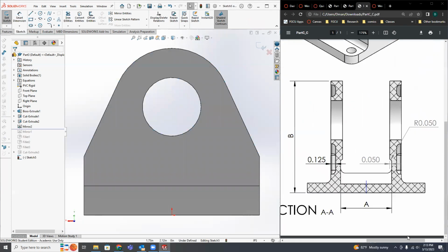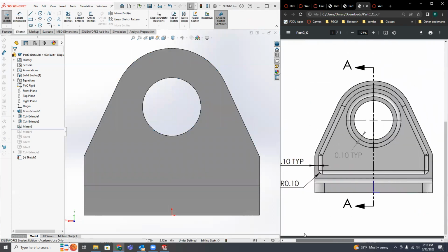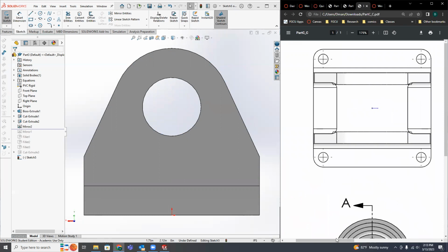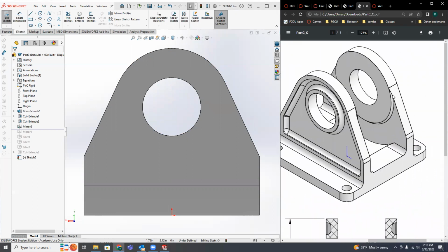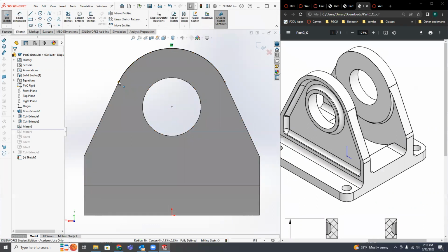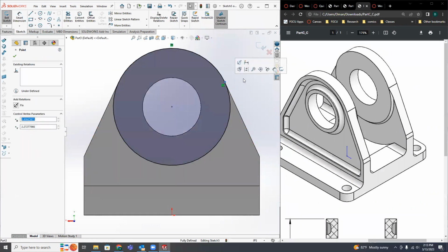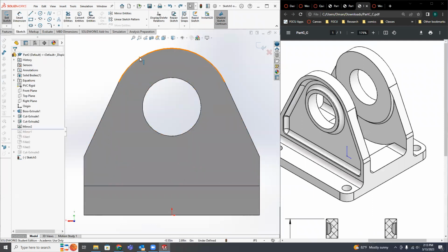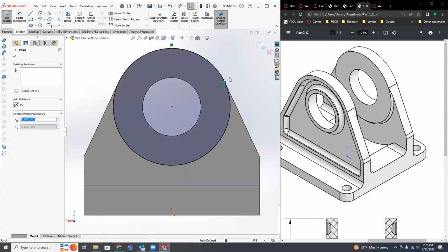Now I'm not given a size for the extrusion of the center piece. But if I look at this isometric view, I can see that it actually extends from the original top rounded face of the part. So all I need to do is convert that feature into an entity inside my sketch and then transfer it from an arc to a complete circle. And I'm going to do that one more time so you can all see it. All I'm doing is clicking the arc, clicking convert entities, and then dragging one of the endpoints around to get a full circle.